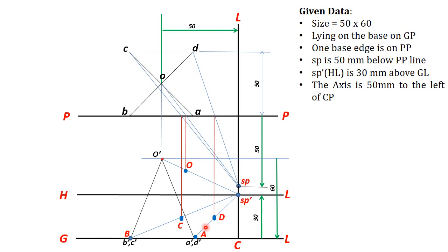After finding all the perspective points, apply the first rule, that is draw the boundary lines first with the dark visible line. So here in this problem, these are the boundary lines BA, AD, DO and OB, and then find a point which is far away or which is nearer to the station points front view and top view.